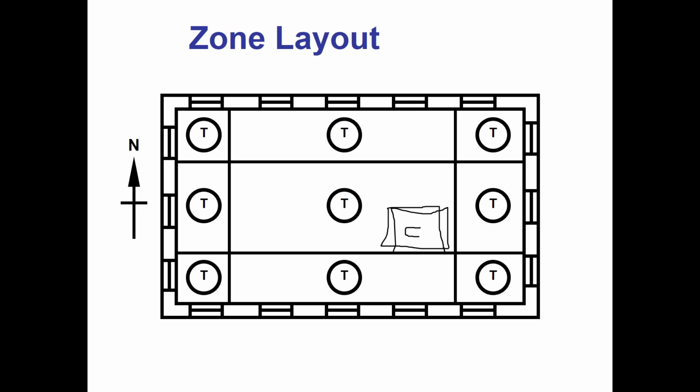The controls guy has the software and the ability to access those sensors, and the air balancer has the expertise and the really good tools to measure things correctly and then help us calibrate those sensors. Then once those things are calibrated, we need to set up the airflow limits on the VAV box. There's going to be minimums and maximums on those boxes to tell me how much air I should be moving,